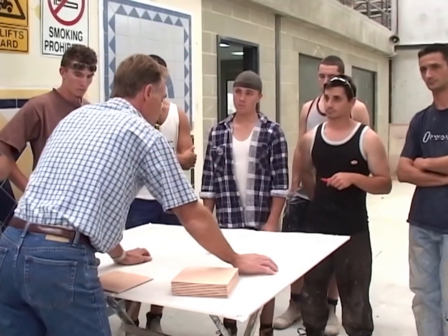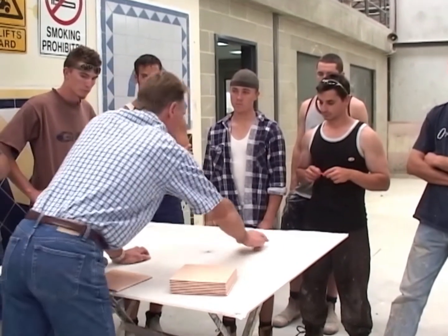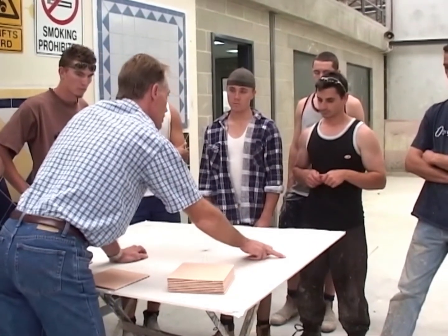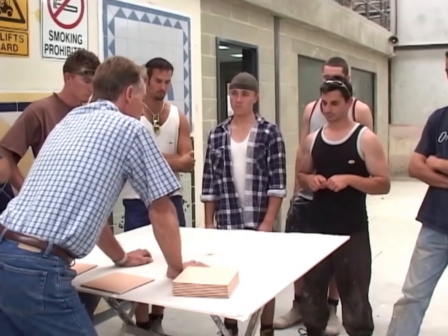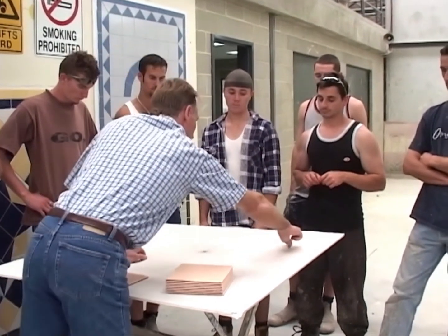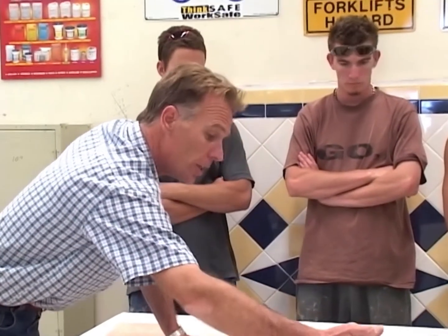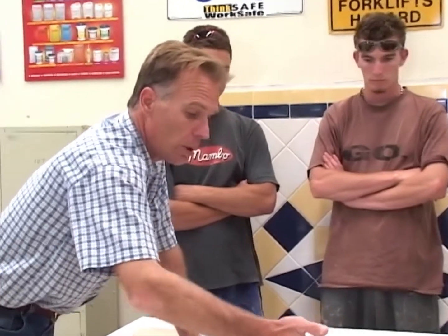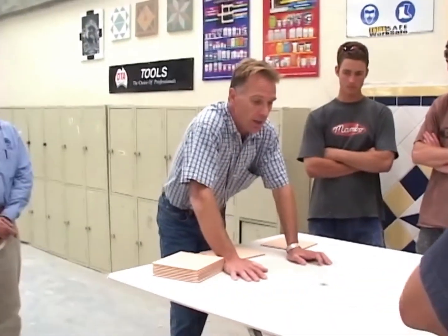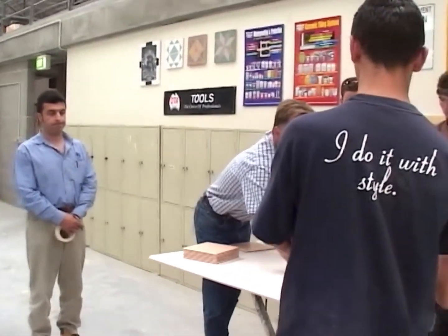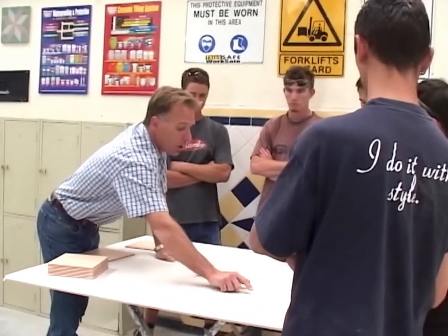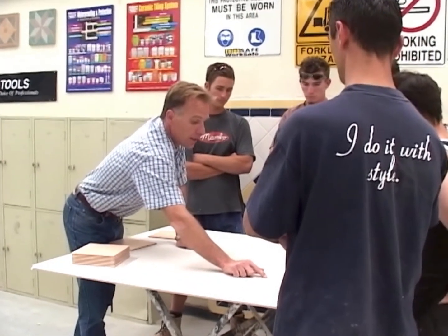And we then divided that measurement of 1/4 of our circumference by 15. That gave us an individual piece from those points. Once you've got a nice equal number of 15 points within your quadrant on your outer circumference, you can then bring those all into the centre. That obviously then gives you the inside measurement on your tile piece as it crosses the inner circumference.